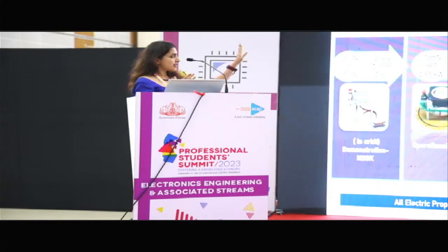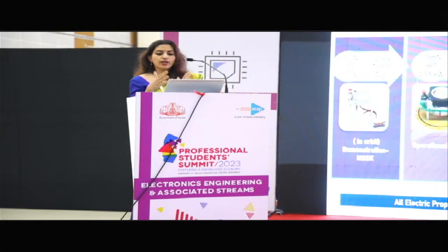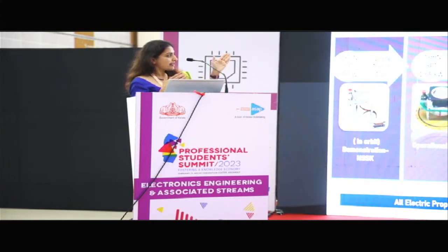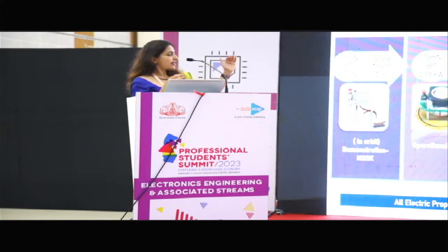You can see a schematic there, it is not very accurate, I have just given a symbolic one. You can see that xenon is stored in the xenon tanks up above, and then you have a feed system where you have so many latch valves. All the things marked with a cross are latch valves, and the gas is taken to the thruster, where we have the anode and cathode. There will be 2 cathodes per thruster, and it will be controlled.